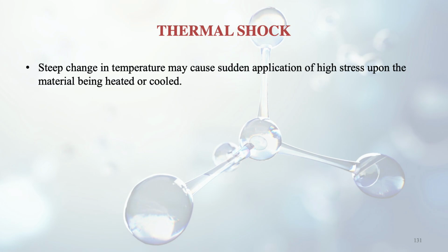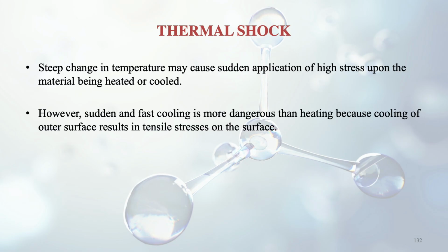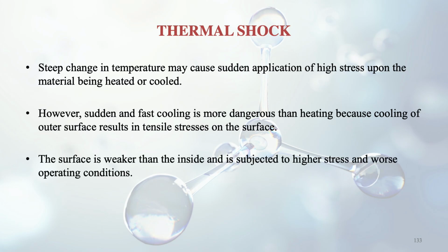After discussing thermal fatigue, there is one more phenomenon known as thermal shock. So we discuss it here. If there is a steep change in temperature, it may cause sudden application of high stress, like the impact we have studied earlier, and this happens because of sudden cooling or heating. However, sudden and fast cooling is more dangerous than heating, because cooling of the outer surface results in tensile stresses on the surface, like we have seen earlier. The surface becomes weaker than the inside and is subjected to higher stress and worse operating conditions.